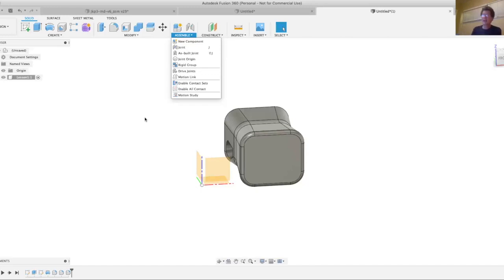Or sometimes you'll actually intentionally import a surface, and then later you'll thicken the surface into a solid. So a mesh refers to a group of surfaces that are connected together, because typically surfaces are fairly primitive, what we call primitive. So rectangles, triangles, things like that. But you have a whole mesh of these surfaces that define a complex surface.